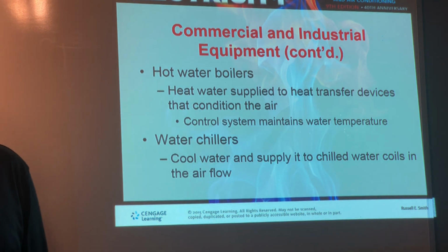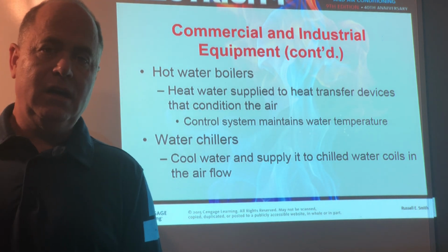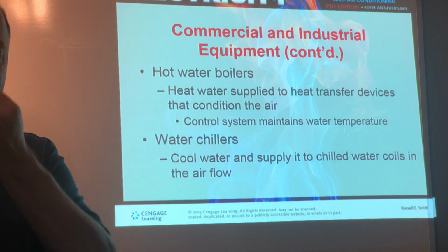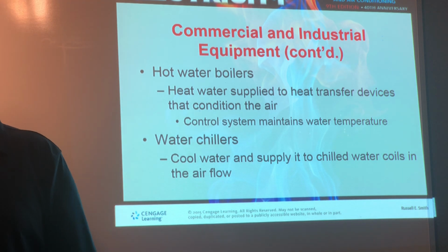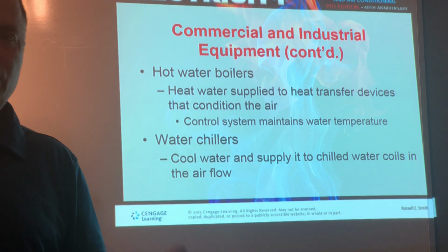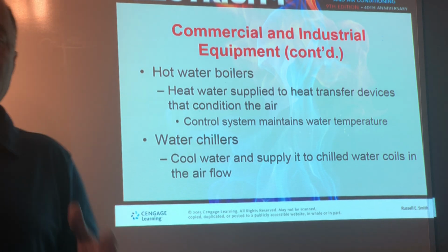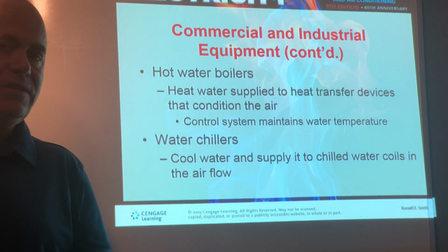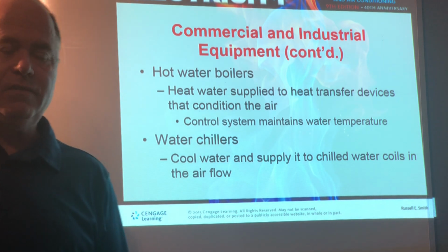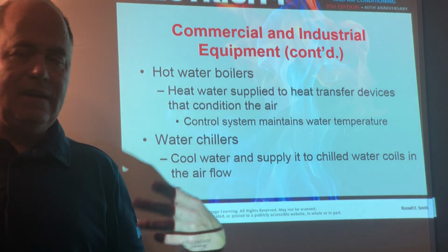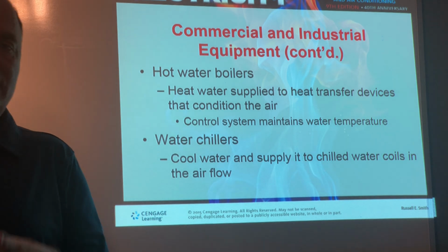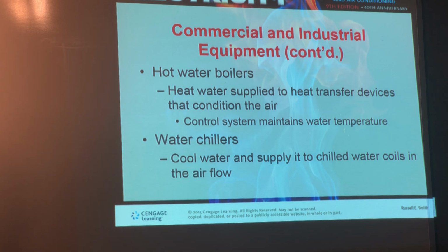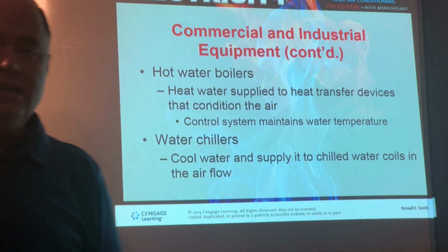And then with our water chillers, again, probably the most common is a centrifugal chiller. And nowadays we usually have these like 150 tons, again, commonly 3,000 tons of cooling, and we have all of this in one location. Then we're just pumping chilled water around. We have less refrigerant that can leak out and harm the environment. It's safer, and you have all the equipment in one location that can be maintained. And again, the boilers are going to be in one central location.